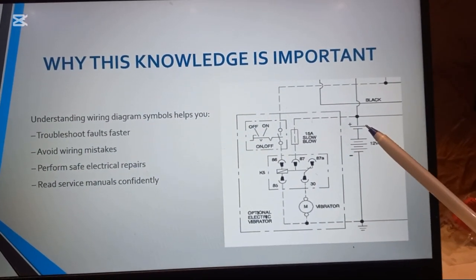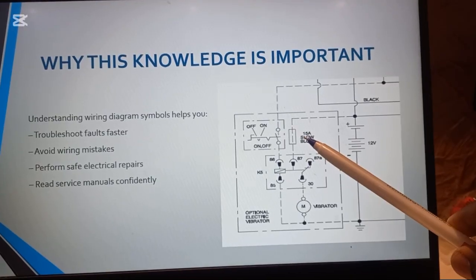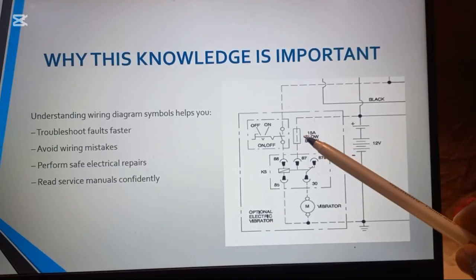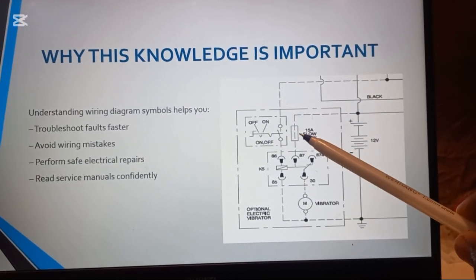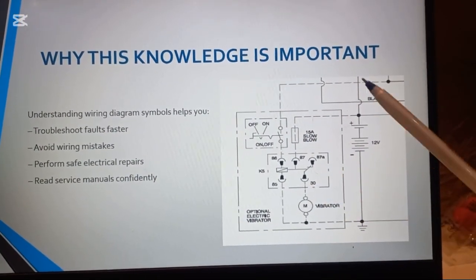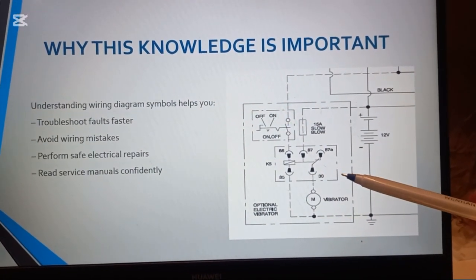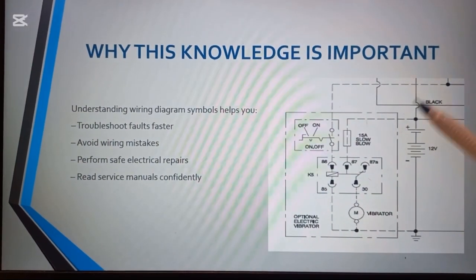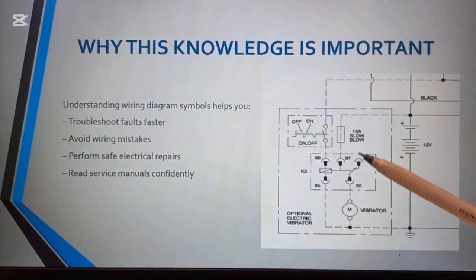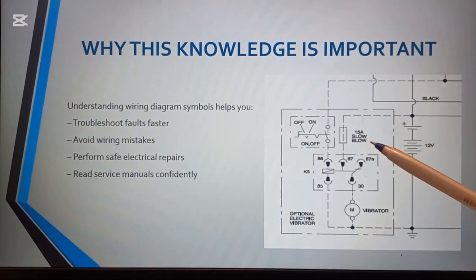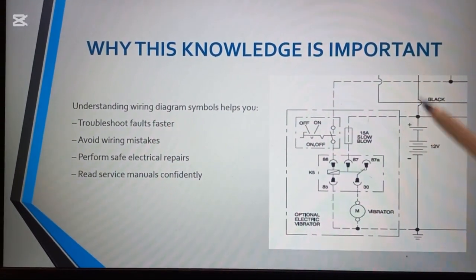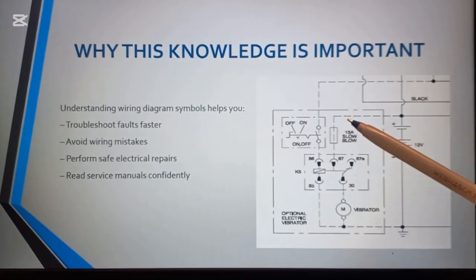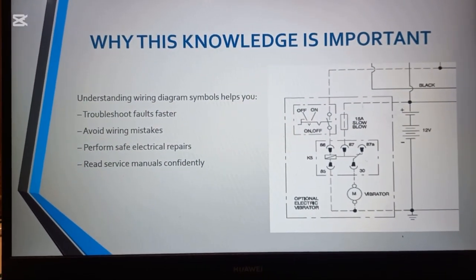See, we have our source here. You will have a 15 ampere fuse. Maybe this is just blown, but because you don't have an idea how it is working, you'll have to follow all the lines to where it is, and you know how big machines are, so it will take you maybe weeks or even months to discover something very small. But if you have a schematic, it is very easy. This is the source. If you don't have power here, you'll check the fuse. If the fuse is blown, you'll fix the fuse, and that will be done.